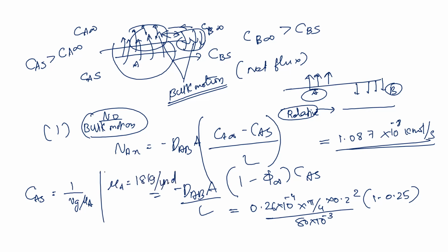Just substitute that and we can determine the concentration. So this is the evaporation rate, in terms of mass, not heat. Multiply the mass flux by the heat carried, substituting HFG of the vapor, and you will get the total heat carried away by this evaporation.